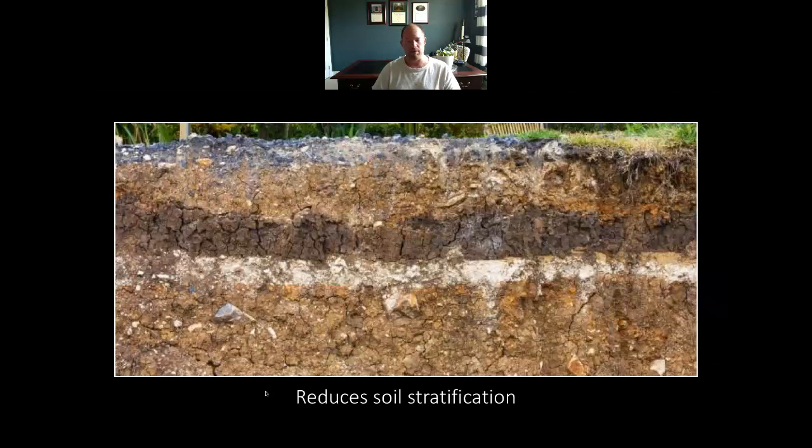But we can also get this going on in a typical lawn or landscape setting as well, especially with poor urban soils. In construction sites or new builds, it's not uncommon to start getting some of this. You'd almost call it a fragipan or a hard layer, a crust that forms that basically becomes impenetrable for the roots and nutrients to move through.